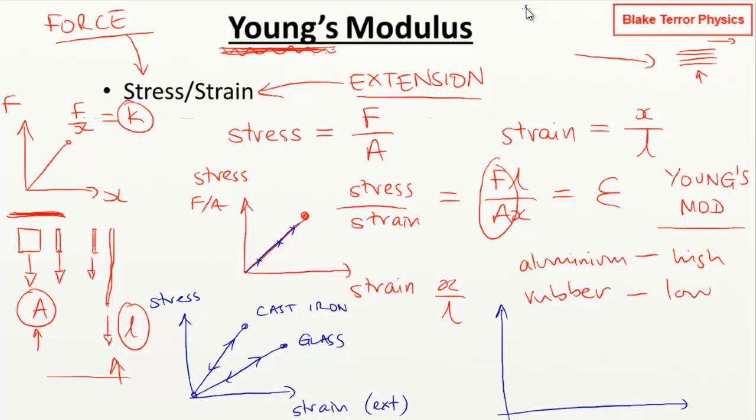Obviously they can take higher loads, but you see the deformation in materials, and you see it with steel, where you get these thin points where you start stretching too much, and it really starts behaving in this plastic sort of way when they're about to break. So this is the sort of inelastic deformation that you're going to get going on in these materials. And low carbon steel is a relatively ductile metal, unlike cast iron, which is much more brittle.